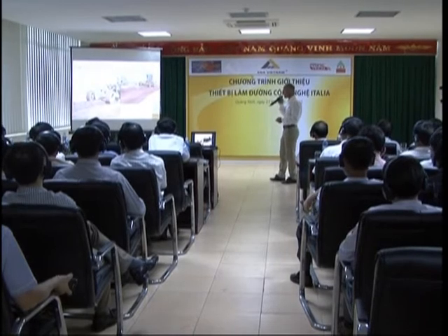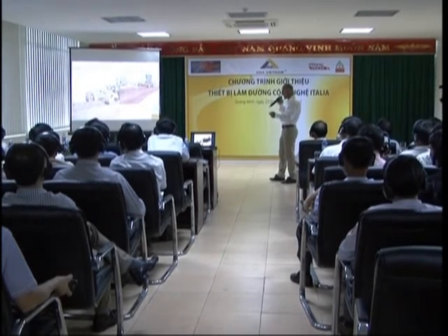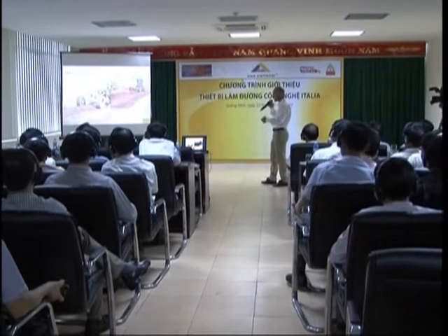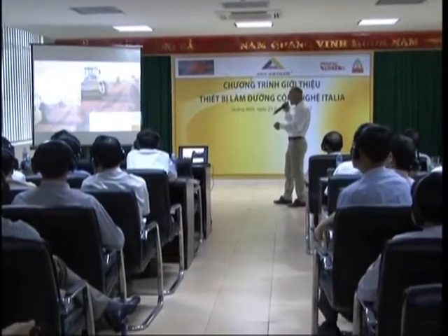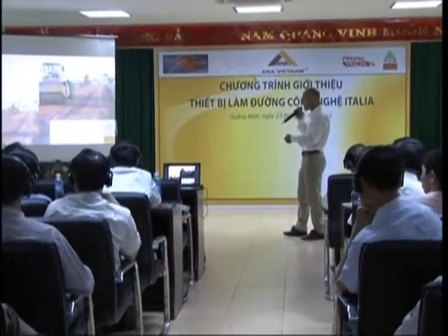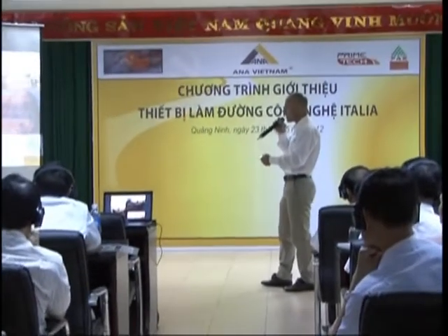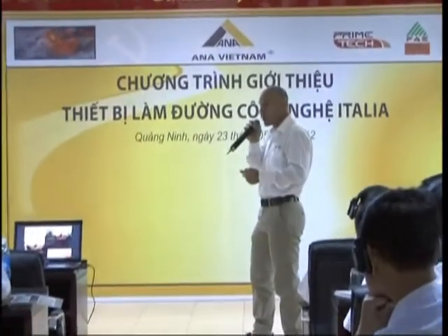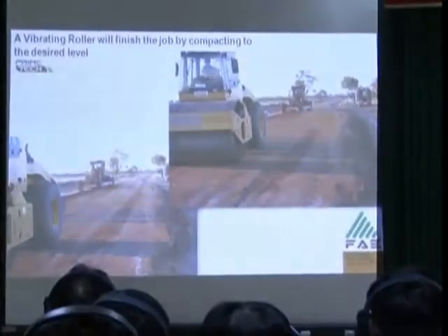When you have added water and mixed the cement, you give a shape. This is giving shape as well. Camber. And then you finish with vibrating rollers. See? This is finished base. Now this base you can drive on, or this is for example a road where they put asphalt on top. They seal the road with bitumen or asphalt. So you can choose. You can drive on it, or you can put asphalt on top. So it's a strong base.